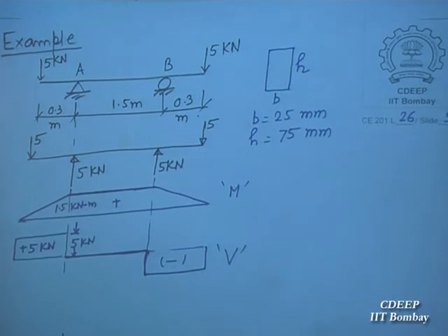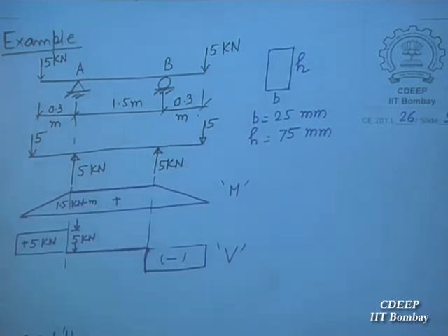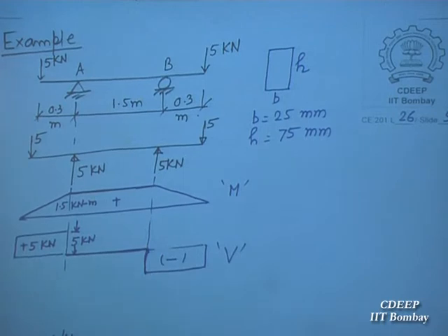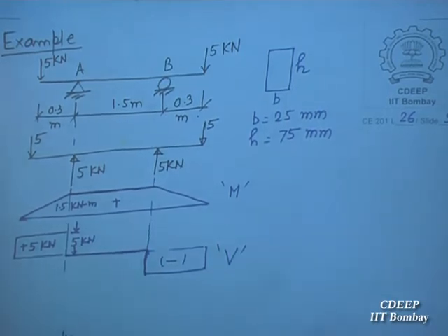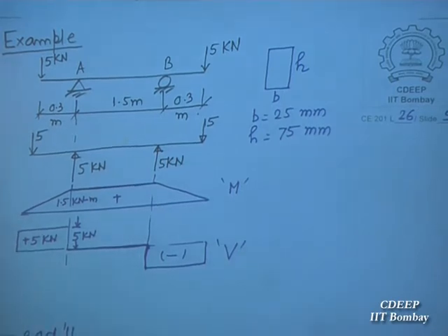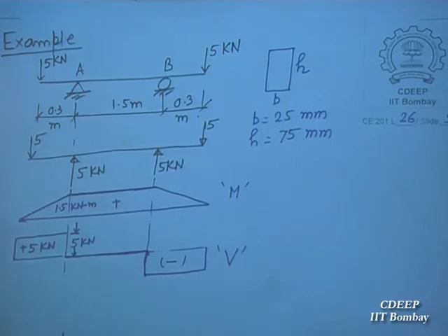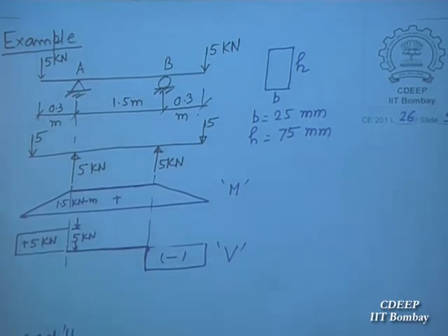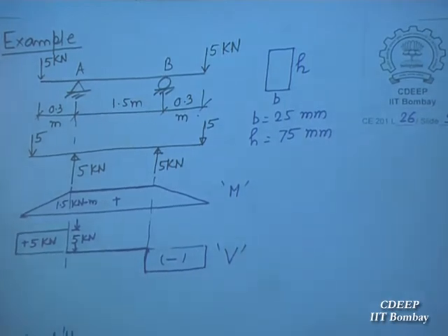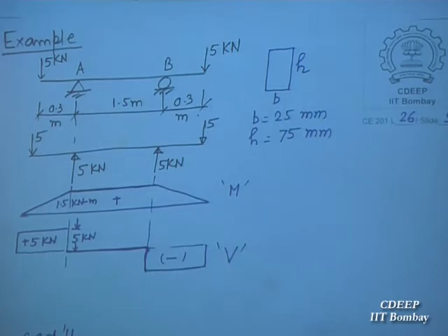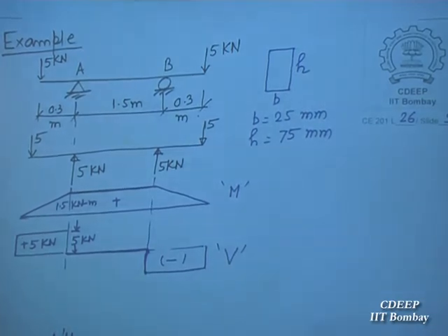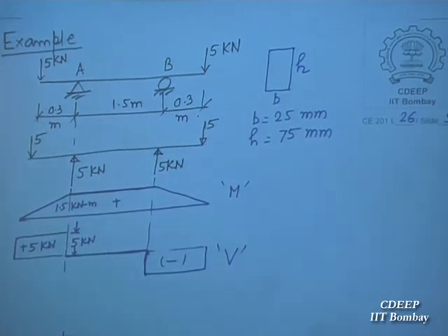You have to divide yield by the safety factor, 1, 2, 1.5. Let us say the factor of safety is 1. This is a simple way. Because material starts yielding, it starts going into the plastic zone. I don't want the material anywhere to go into plastic. So what is your best way? You see that nowhere it goes beyond yield stress divided by 1.5. If you know the material very well, then you give a smaller factor of safety. If you know less, then you give a larger factor of safety.